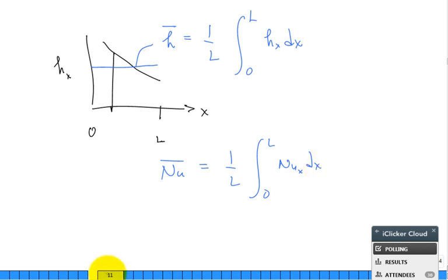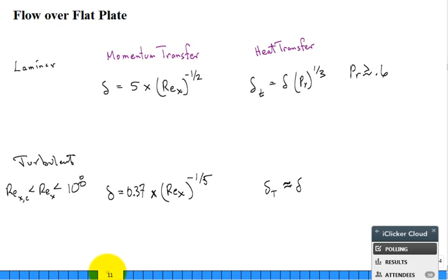Now, you have flow over a flat plate. You studied this before just from fluid mechanics. We just derived using Blasius about this laminar condition. We've even gotten how thick the boundary layer is. Well, with a little bit of work, you could find the thickness of that thermal boundary layer, the laminar thermal boundary layer. What did they put on the subscript on this delta?